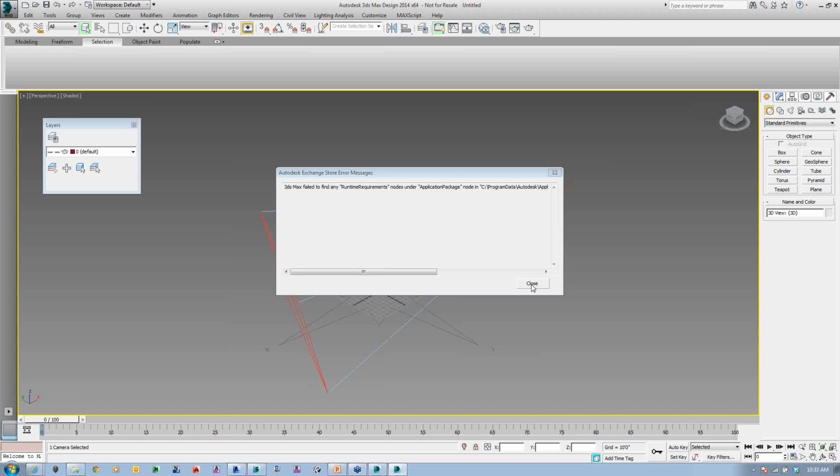Now, if I wouldn't be doing this at the end of the day, I probably would restart my machine, make sure I've dumped my RAM and cleaned all the stuff out of there. So it's good to fire off a new machine. That's one of the processes I'd say to go and do: make sure that you are running with clean versions of the software, that you haven't fired up a bunch of things on your machine when we are rendering. I always do this when I'm just rendering from Revit. Close out of Revit, reopen Revit, then start your rendering process. The same would be true for Max or Showcase or anything else.